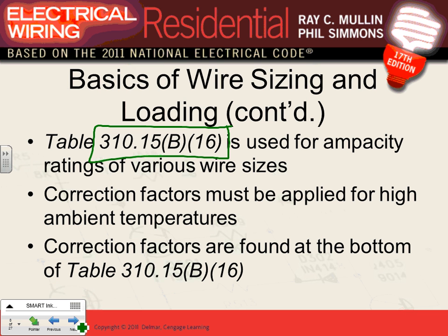What's the ambient temperature in the area? Is it 30 as it should be, or is it 50 Celsius? 30 or 50. So these are 3 factors that are very important when you size a conductor. And then there's other auxiliary factors. Do you want to use copper or aluminum? You have to decide, are you using copper conductors or aluminum conductors?